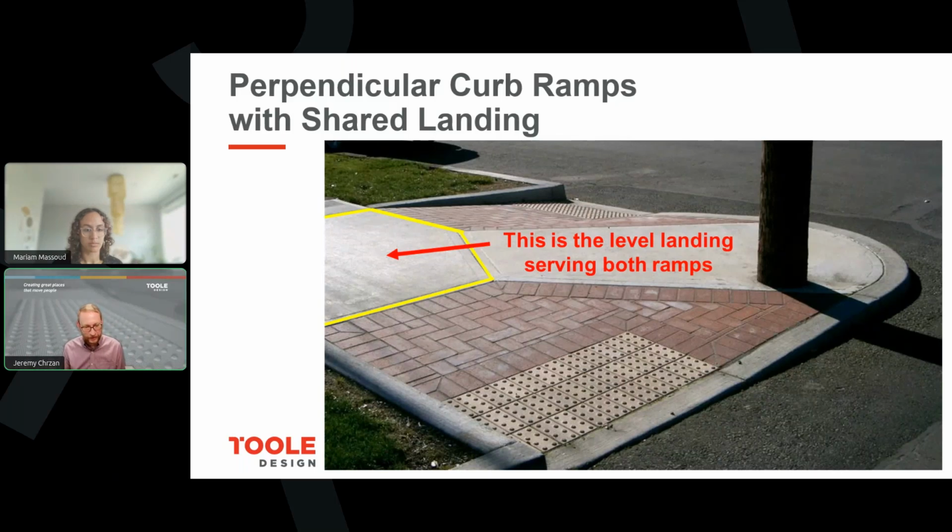And again, we have to sort of identify the design that will work within the constraints of our individual site conditions. I'll also note that this image is showing the use of the brick detectable warning surfaces. We generally don't recommend those because they do tend to be dislodged and require a little more maintenance. The nubs on them chip off, and so relying on the plastic or cast iron is usually preferable.